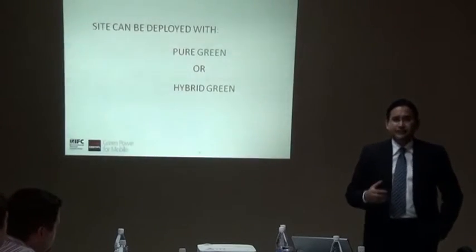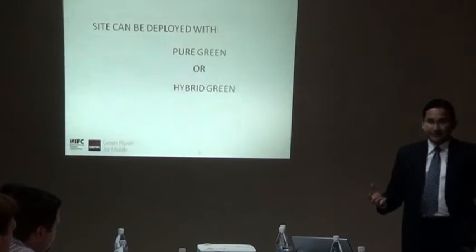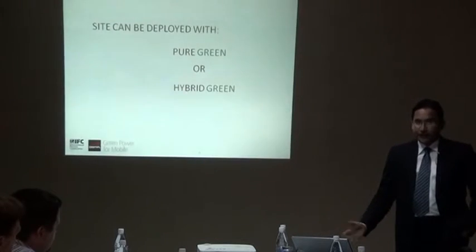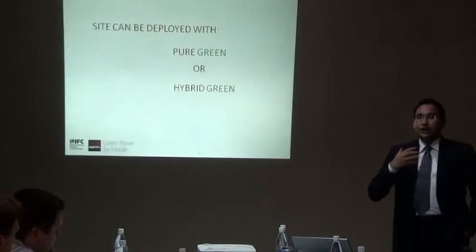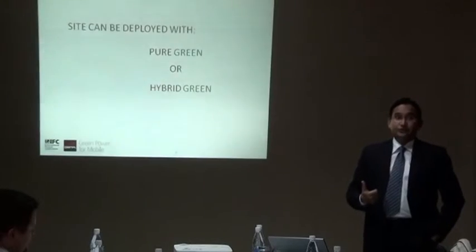Hybrid green is essentially having a diesel genset plus an alternative power generation source. It can be diesel, battery plus PV, or diesel, battery plus wind turbines, or diesel, battery plus other sources like fuel cell, and so on. It's a hybrid approach where you want to optimize your diesel genset use and reduce the usage significantly, but at the same time maintain maximum uptime of your base station. So both aspects have to be well synced up. Hybrid solution is something we have been seeing significant deployment of across the world right now.